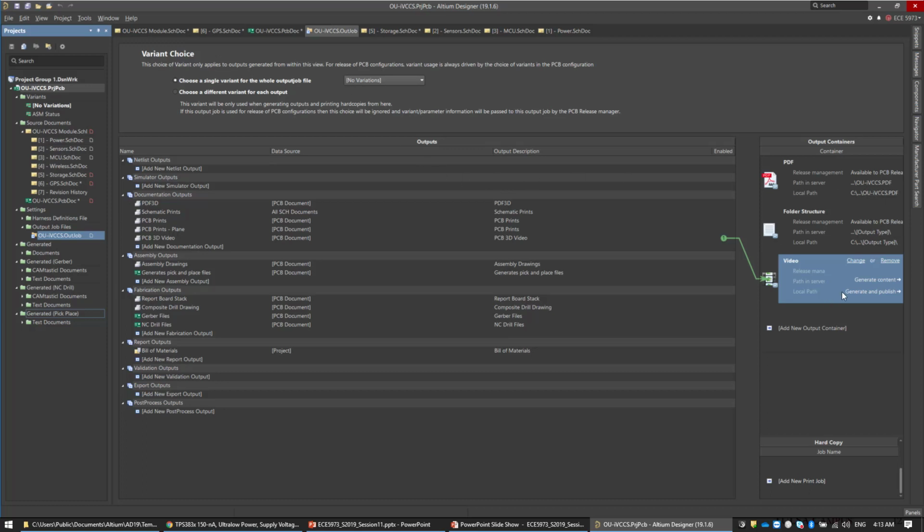Now, this is just simple example how you can design with 4-layer PCB. Use the top and bottom layer for signal and use the inner layers for ground plane and power plane. And try to separate or use split plane for your powers. If you have multi-rails, you can use regions for different rails as well.